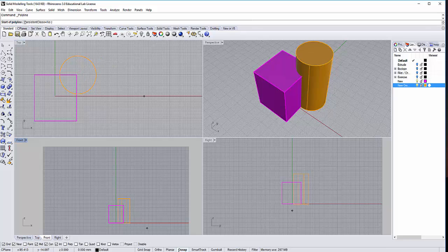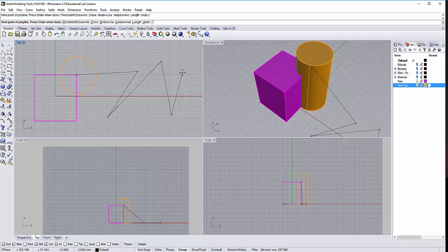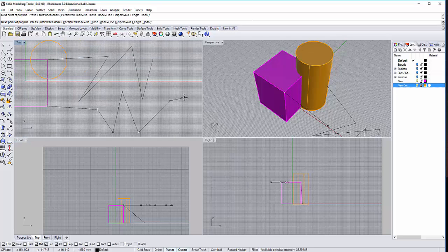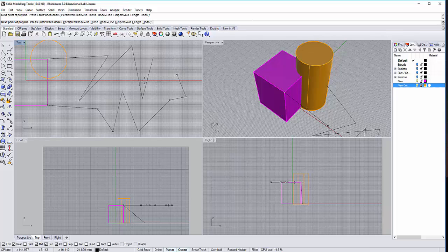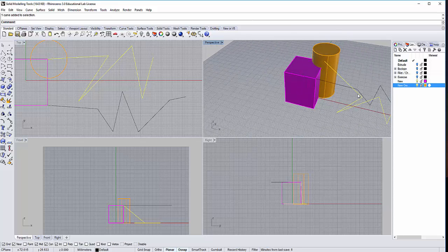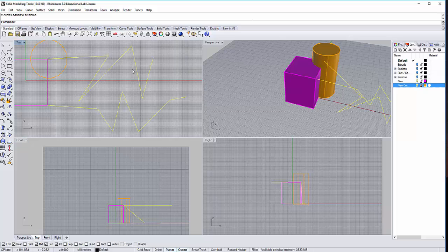However, let's say, for example, if my planar is off, when I draw a line here, it would directly snap to the floor. Can you see? It doesn't give me a straight line. However, let's say my planar is on. I draw another line at this side, somewhere here. Notice the difference here. One with planar on will give you a straight, nice flat line. However, the other one will give you something snapped to the floor. Can you see the difference? Make sure when you are working, have your planar on. Try those buttons first.